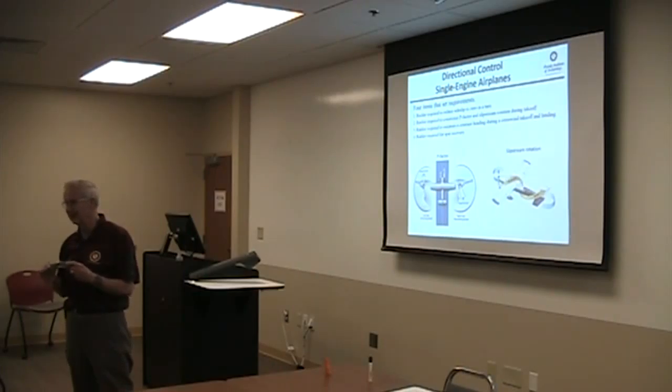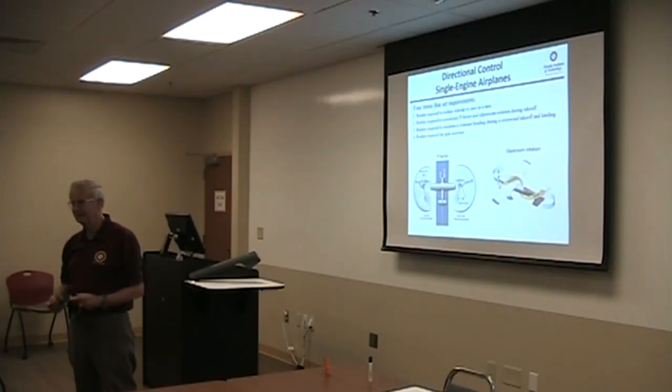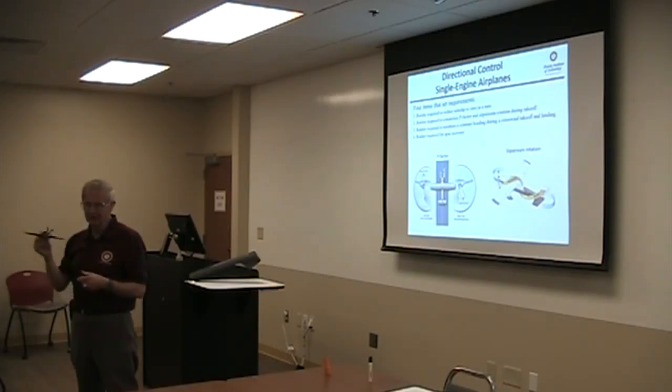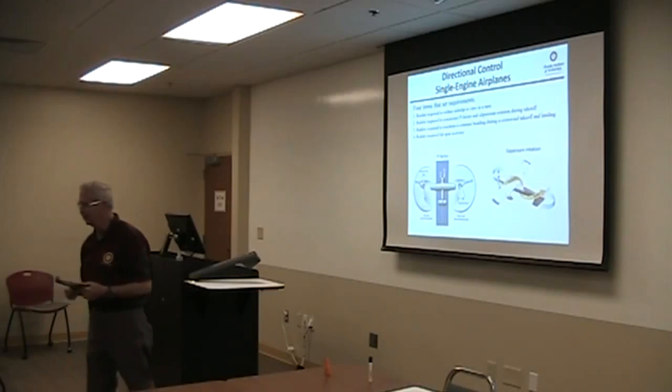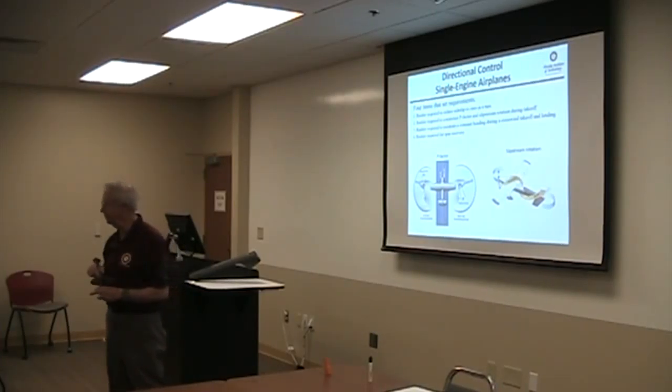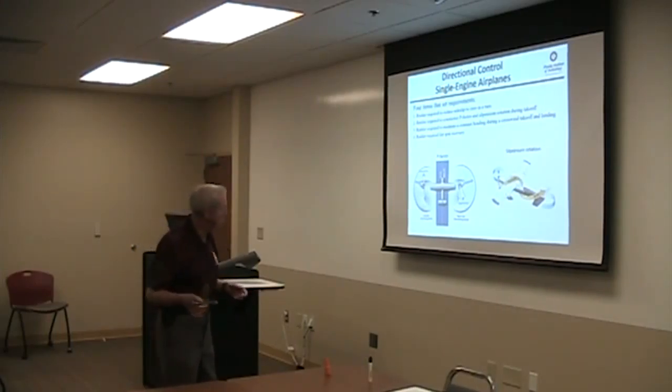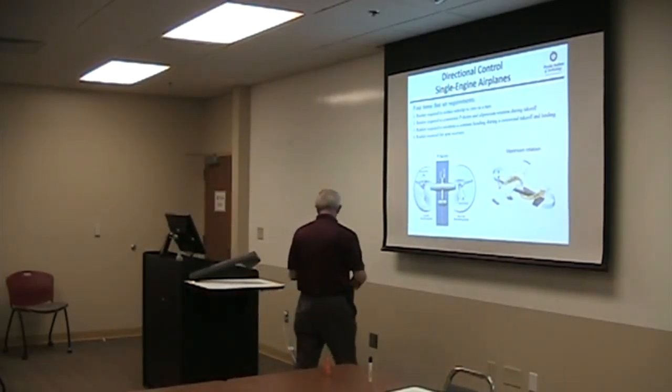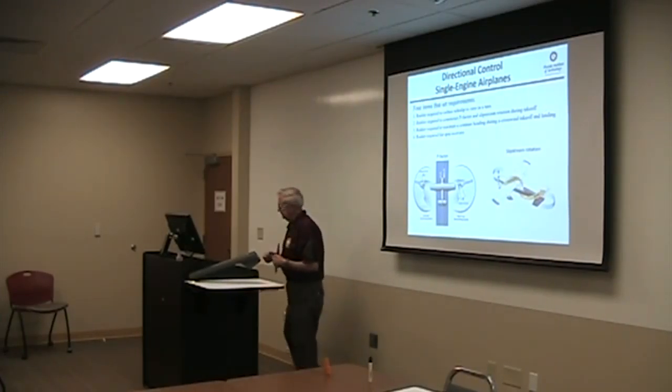Because the spin is at below stall speed. The airplane's descending. Its forward velocity, if you spin from high enough, becomes vertical. Initially, there is some forward velocity, but still, if you hit the ground in a spin, you're more likely to survive it than if you hit the ground on the recovery, which is generally around 120 knots in most of today's airplanes. So the spin recovery thing, for the one-turn spin, is kind of going away.